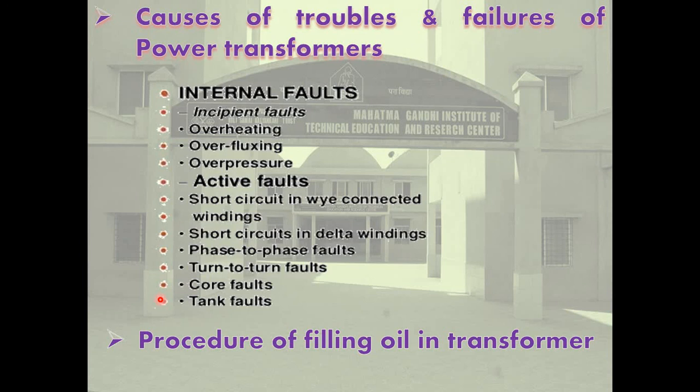Okay. Now evacuation, oil filling, circulation, and standing time after circulation. It is also a main important part. Before application of voltage, a certain standard time is necessary before applying the voltage.